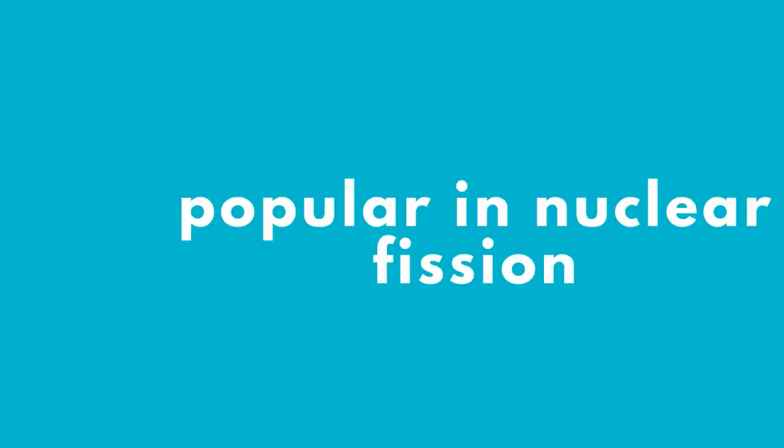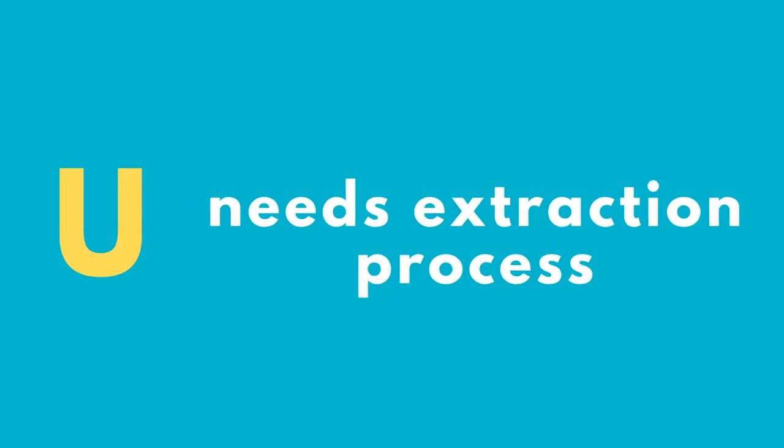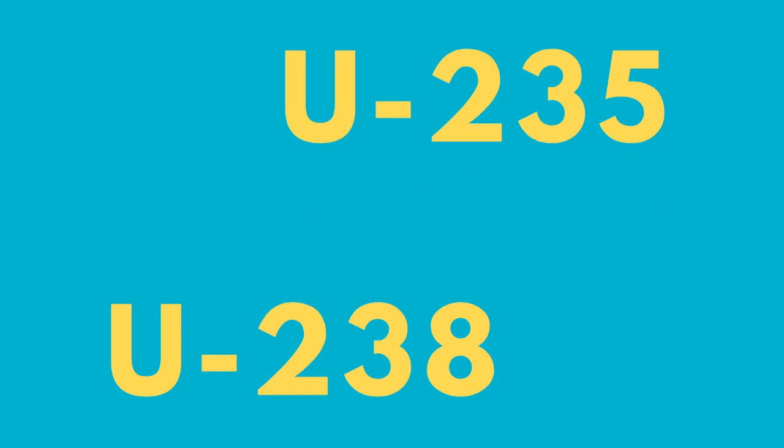So to recap, uranium fuel is highly popular as an energy source for nuclear fission. It is extracted from underground deposits, hence the need of an extraction process, specifically a leaching stage. There are two types of leaching, acid and alkaline leaching. Acid leaching is generally cheaper, while alkaline leaching produces a much purer product. Of the two uranium isotopes, we mainly desire U235, hence the need for an isotope separation step, which is most commonly a centrifuge.